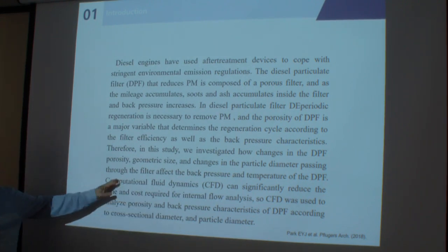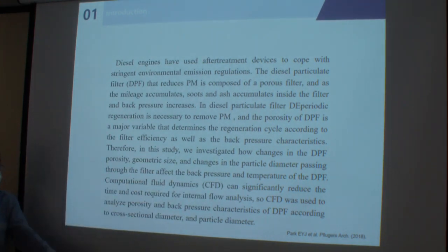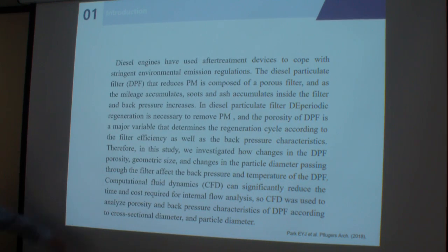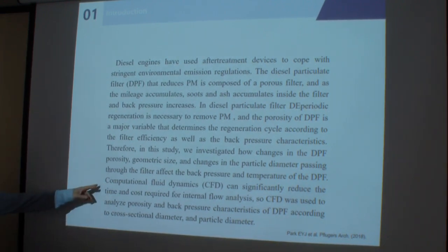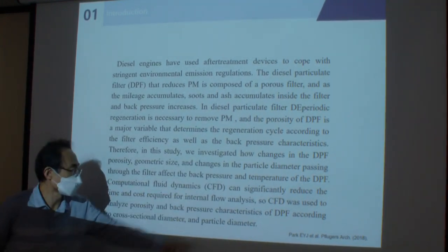In this respect, the temperature of DPF is very important, and back pressure is important because we need to remove the accumulated PM inside of the DPF. For the investigation, I used computational fluid dynamics.